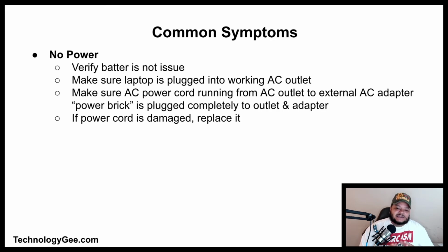What if your device has no power? So if a laptop has no power, you need to verify that the battery is not the issue. You need to make sure that the laptop is plugged into a working AC outlet. You need to make sure that the AC power cord running from the AC outlet to the external AC adapter, also known as the power brick, is plugged in completely to the outlet and adapter. And if the power cord is damaged, you need to replace it.